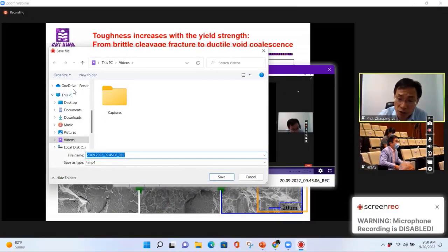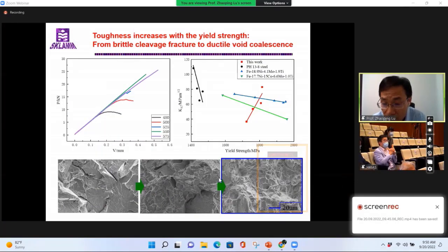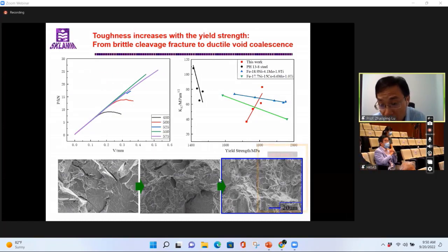We observe that to achieve the high toughness, we have to add this moly inside. The moly actually creates some moly clusters on the surface of the nickel aluminum. So that's the key. We have to optimize the heat treatment process to achieve the high toughness.